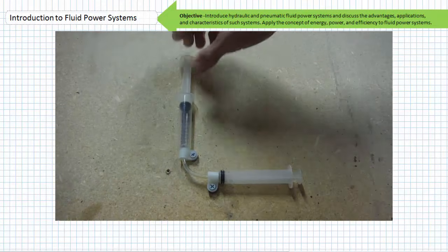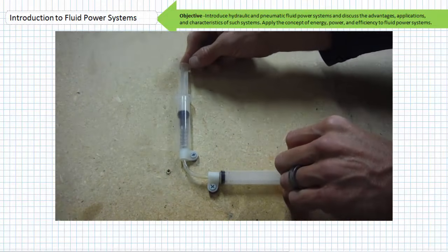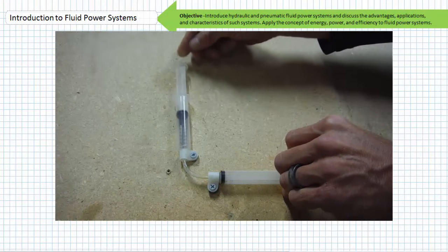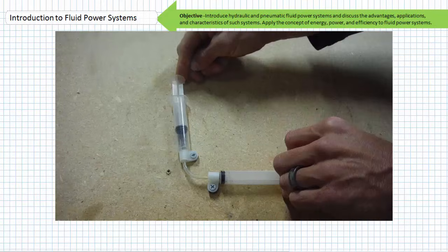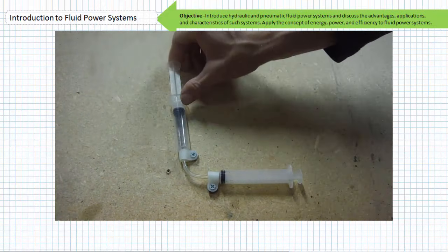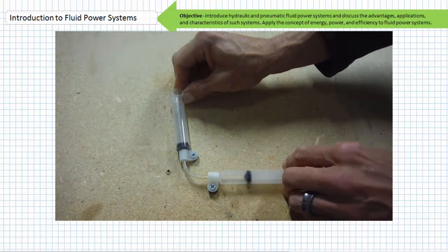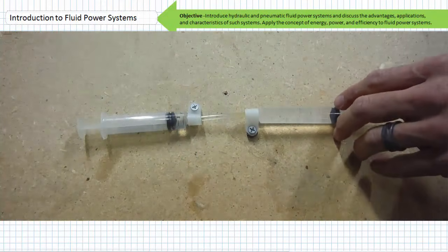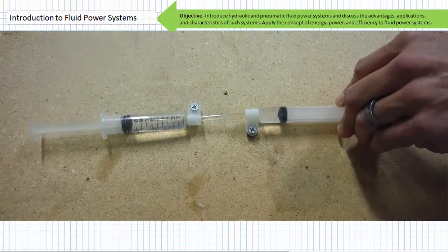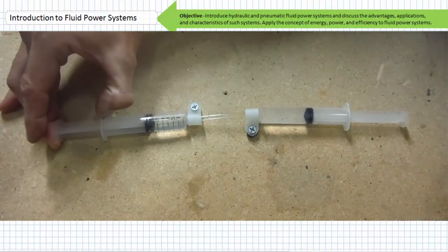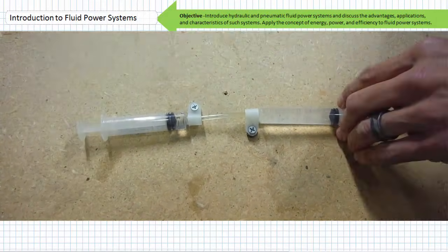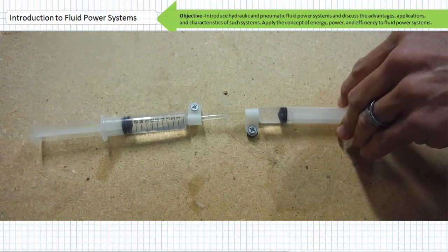There's a bit of lag in actuation. Additionally, note the sponginess of an actuator supporting a load. These observed characteristics are due to the compressible nature of air and something that must be accounted for in a pneumatic system. In contrast, when the two syringes are filled with water and capped off, the entrapped water is now a confined fluid, and this is a basic hydraulic system.